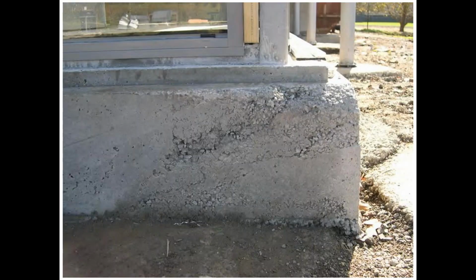Otherwise, there's an example in the corner of concrete, a big concrete slab there that hasn't been compacted well, especially in that corner. You can see how open it is, but how strong do you think that is? What's even worse is if you look up a bit, there's actually a steel column base on that corner, which is taking the load of a 2- or 3-story building, and it's as weak as anything on that corner. So that's straight out incorrect compaction or lack of compaction that's caused that problem.